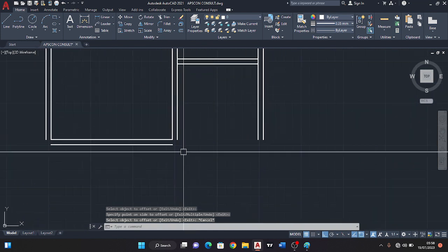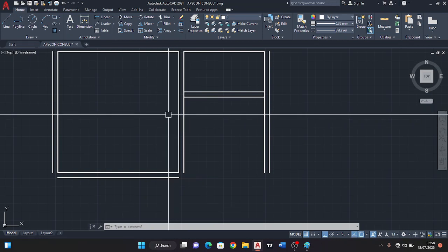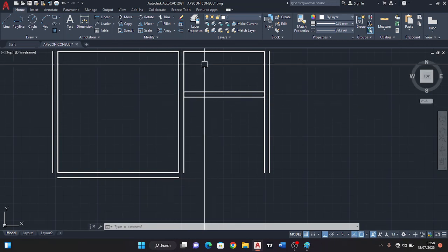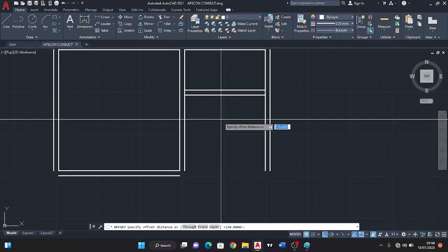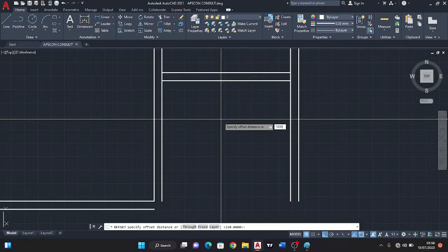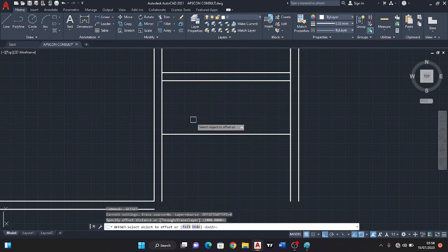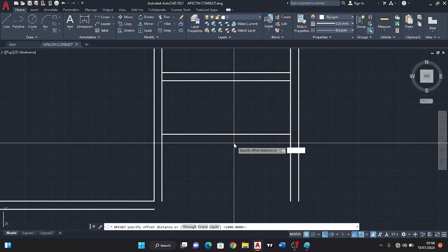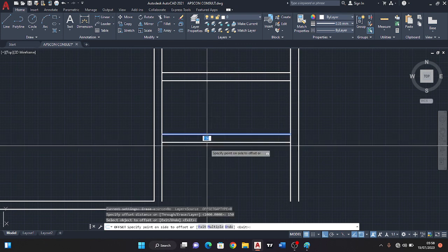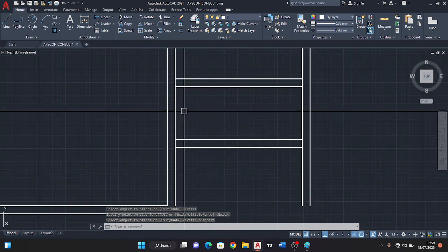After that, what I'm going to do again is create a lobby whereby I can enter the lobby and switch into the toilet or into the kitchen. Now let me create that small lobby. I can just say let the width of that lobby be 1000. Type in the 1000 from my offset, and after the lobby there's a partition wall of 150. I select my offset, type in 150 and say okay, and from there we've gotten our 150 wall. Here is 150.